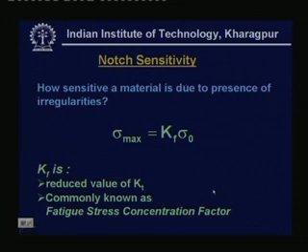In other words, how much intensity of the theoretical stress concentration has gone inside the material, that is called the notch sensitivity. So, notch sensitivity physically tells you whether the material is totally sensitive to the notches present or it is insensitive to the notches present.